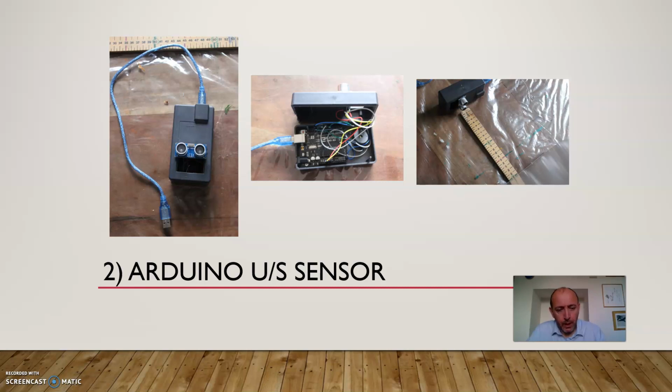Okay. Now, just to let you know, this experiment is done in a slightly different way compared to the last experiment with the Pasco motion sensor. What I did is I varied the target distance from 10 centimeters to 100 centimeters. And I measured the total ping echo time. So that means the total time, transmission and receiver time, up and down.